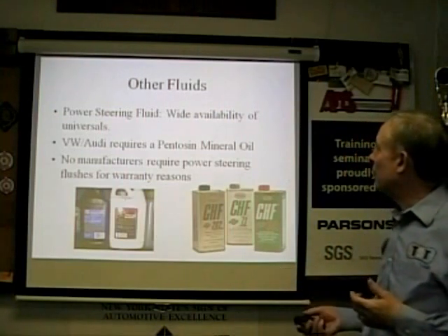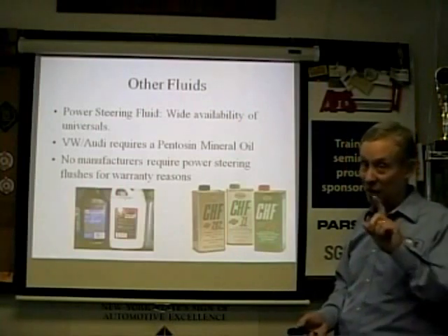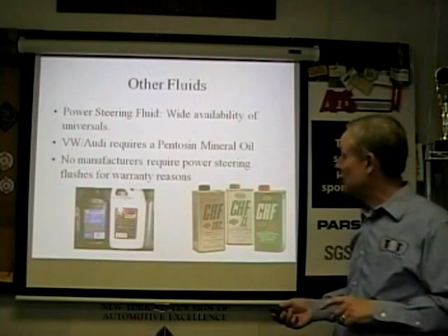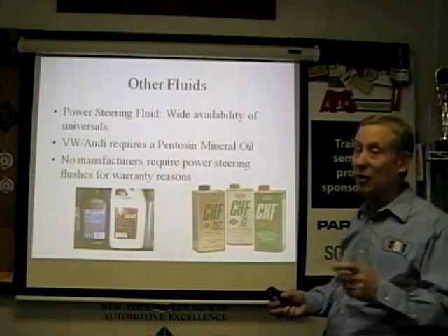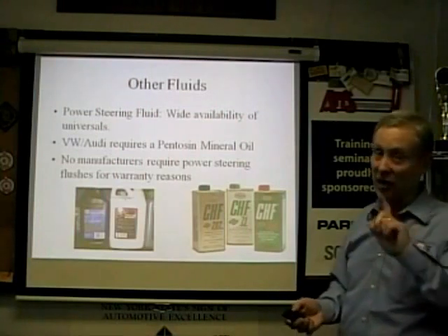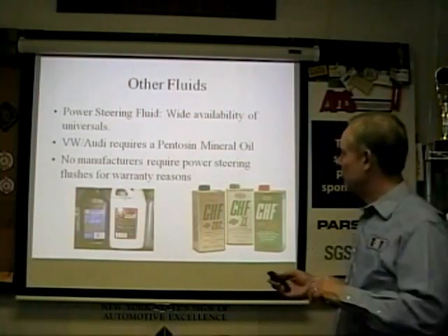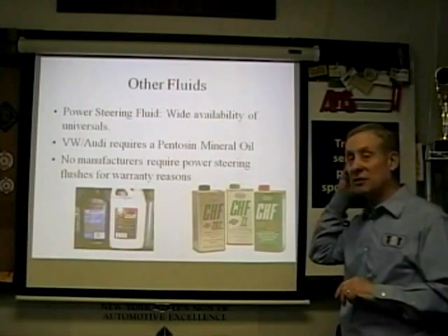VW Audi requires Pentosin mineral oil. You got to read the cap or read the spec on this. The early ones were CHF 7.1. The later ones are the synthetic 11S. You got to make sure you got the right one. They're both green. No manufacturers require power steering flushes for warranty reasons.